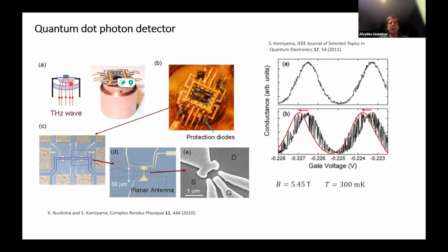And then it should be placed in a terahertz waveguide. It also has a substrate lens here, and then the terahertz wave comes through a waveguide into that cryostat. So this is an example of the built-in crystal. Now let us change the gate bias voltage and see the conductance of the structure. This would be the dark characteristic.